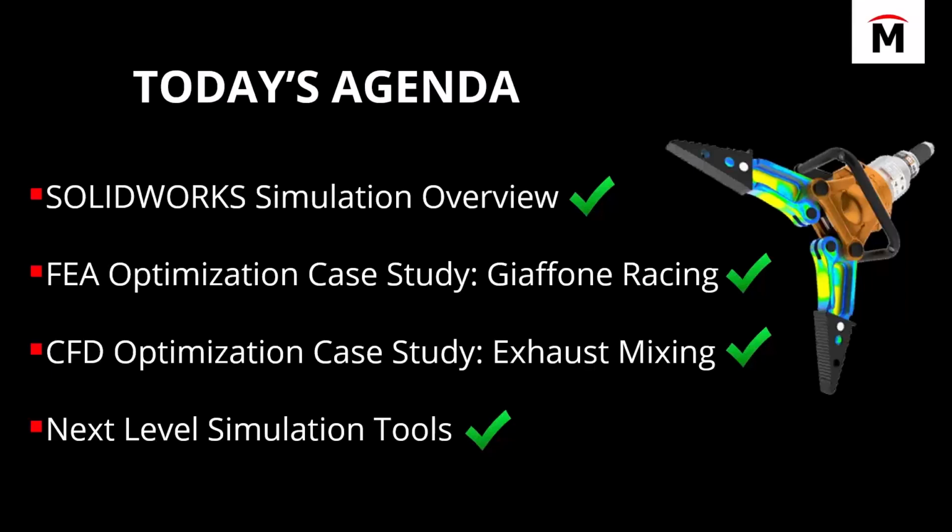Yeah, I just should say the biggest thing, the number one thing for simulation speeds is in the setup. It's in the meshing, the contacts that are used, any simplification you can. So that's a big point of our training curriculum, like I mentioned earlier with meshing, is efficient solve times.